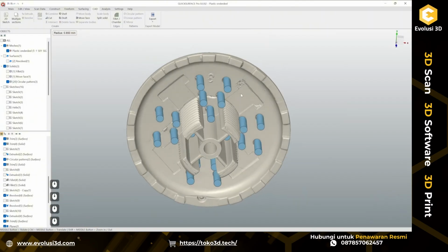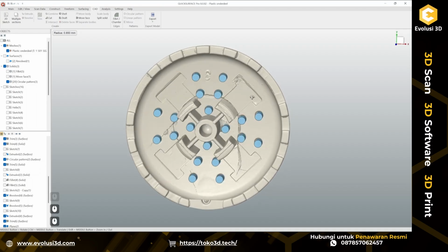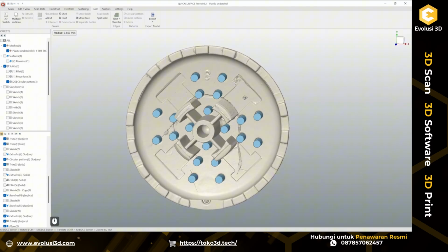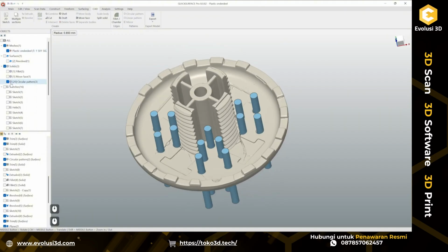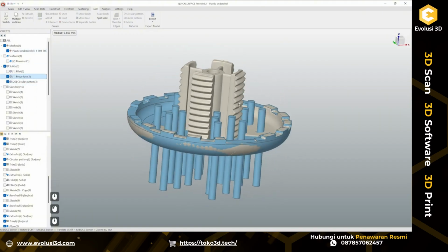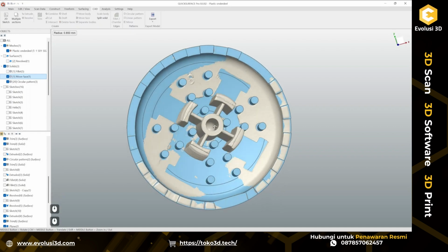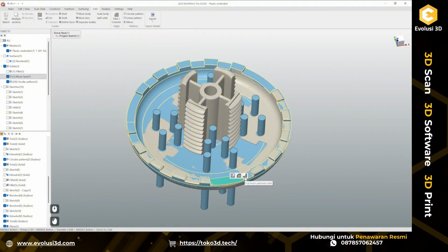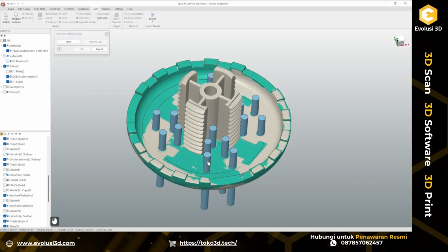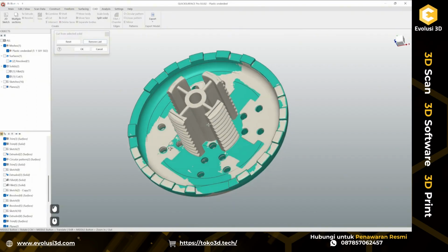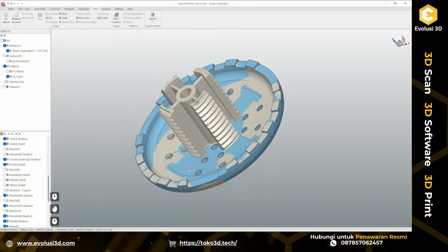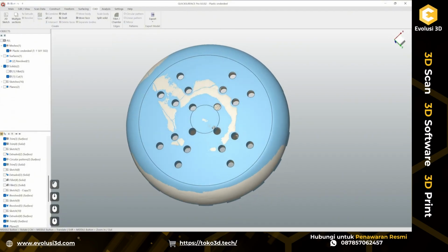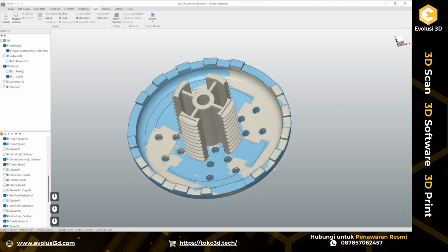Well, first of all, this is plastic part, and we can never know how perfect was it. And I will assume I want to create this as a more or less perfect cut part, so I'm just going to use this pattern here. And this time I will use this option count cut from selected solid and selecting my pattern features and cutting them away. Okay, so we're here right now.